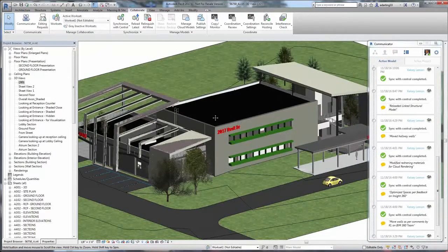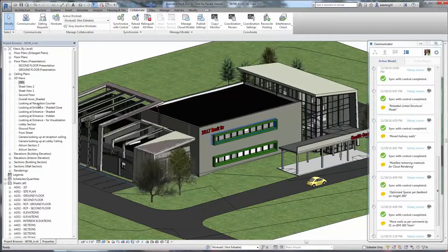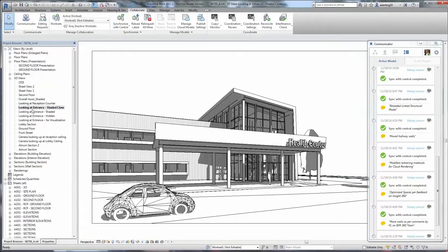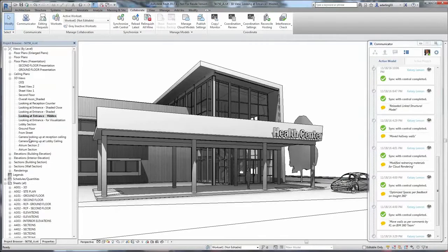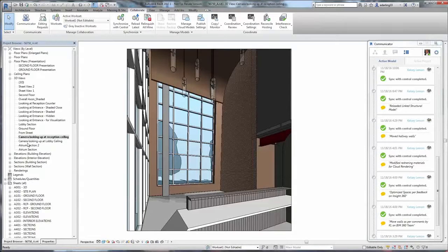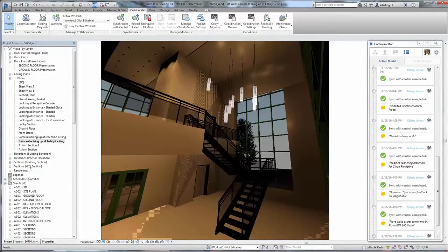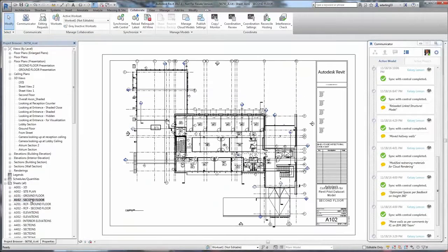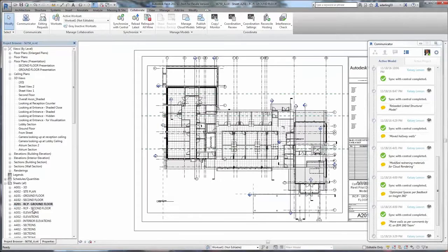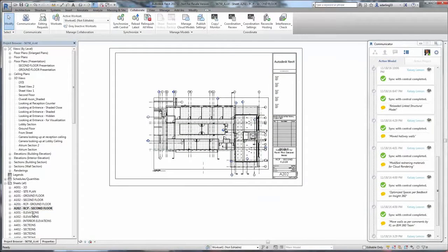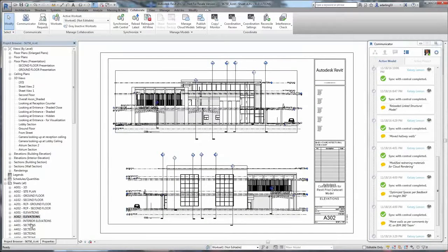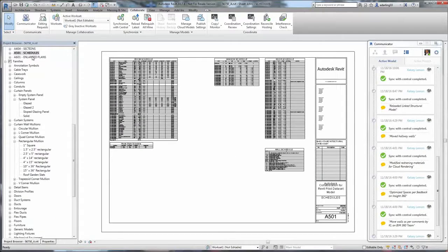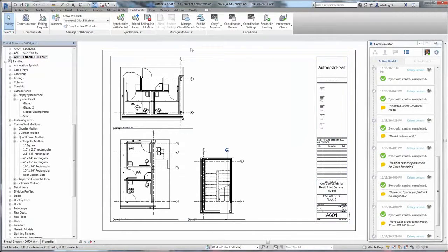The next set of exercises requires at least one additional project member to be active within the project and using the same model file, 56750_A. This user will be referred to as User 2. User 2 will either have to have their own subscription of Collaboration for Revit or a 60-day trial of their own. If this model has been closed by you, the User 1, then you'll need to reopen it and zoom to the area around rooms 1201 and 1301 in the ground floor view, and then select the building elements to ensure you have ownership of them.